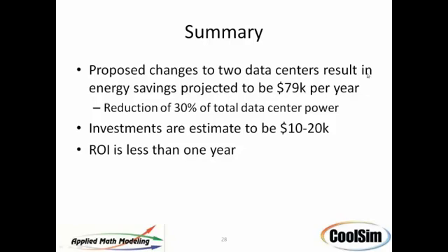Well, I think it's a mixed bag. It depends on the configuration of the data center. If they have the capacity of delivering what that booster wants from the raised floor, fine, it's going to work. But otherwise, the risk is that you're actually stealing air from other areas of the data center. So in a situation where you're supplying 10,000 CFM from the CRAC unit and your racks want 15,000, putting a fan tray in place isn't going to help.